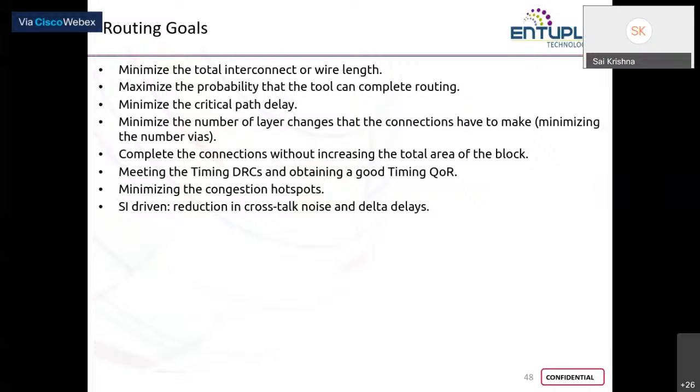And when you have two parallel nets side by side, they act like parallel plates of a capacitor, and a capacitance is formed between both the metal layers. So you have to also make sure that this capacitance does not involve crosstalk of signals or extra delays.